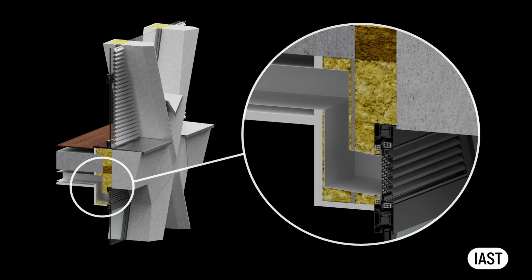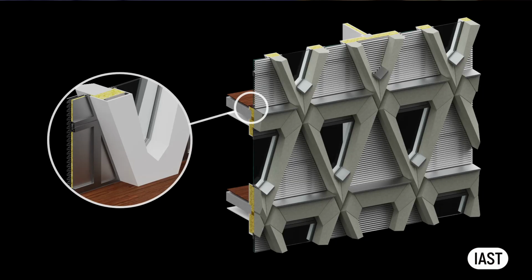For this reason, we have opted for non-openable windows in the diamond-shaped apertures, with the top part of the aperture designed for the ventilation outlet with louvers. The duct for the ventilation outlet can be located in the void behind the ceiling. If the building is only mechanically ventilated, there shouldn't be any further requirement for openable vents in the facade, and the triangular apertures could be closed off with aluminum panels.